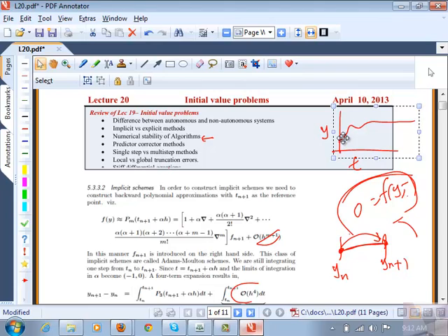Okay, so if you're doing the simulation for flow past a cylinder around a Reynolds number of 160, but you choose the steady state option, stationary, what would the numerical method do? At that Reynolds number, there is no stable steady state solution. So you're asking it to use the steady state algorithm, the Newton iteration, for example. Either it blows up due to numerical instability, or the iteration will oscillate. That's an indication that you need to do a dynamical simulation properly to get the true dynamic response.